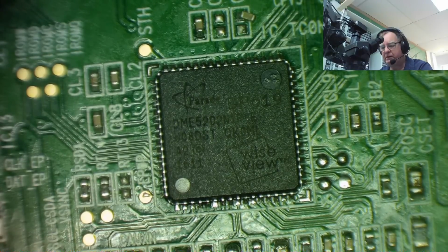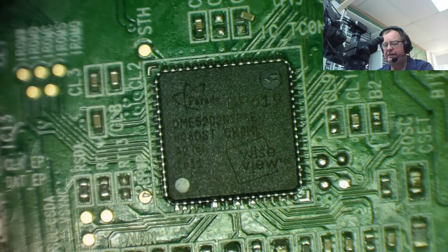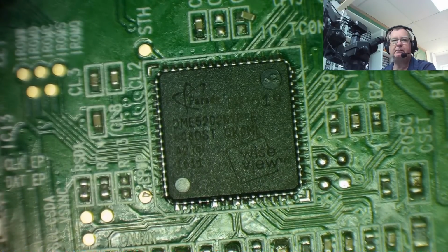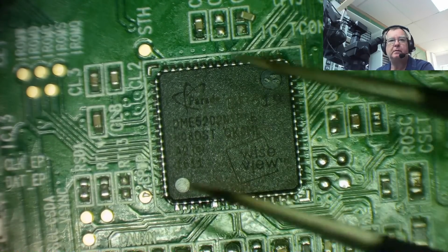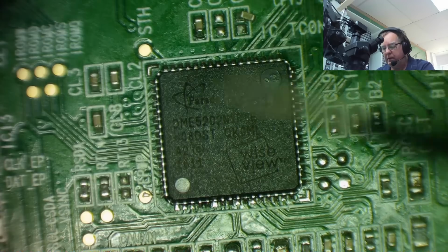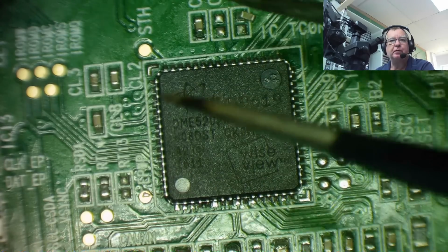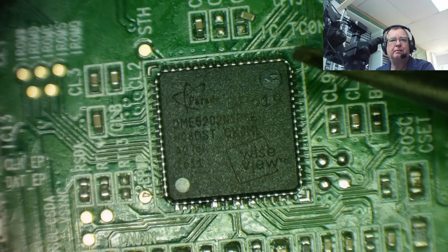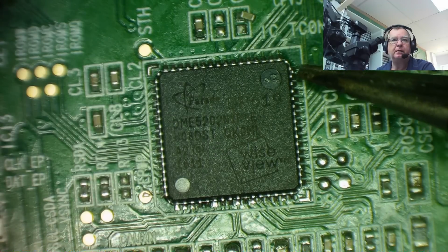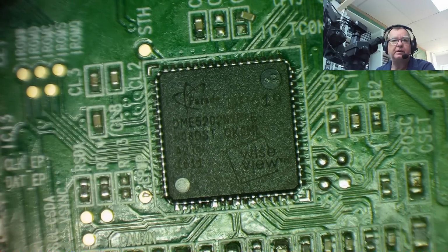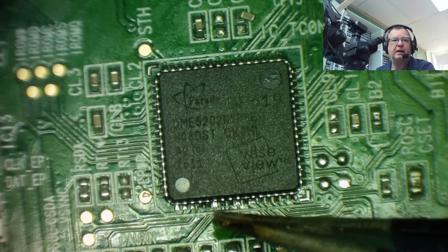Guys, this is the screen that we fitted the replacement chip on, the video chip. And it looks like I've got solder around pretty much all the pins. I think I might have a solder bridge up here on that first two, and maybe a couple down the bottom edge, maybe one there.